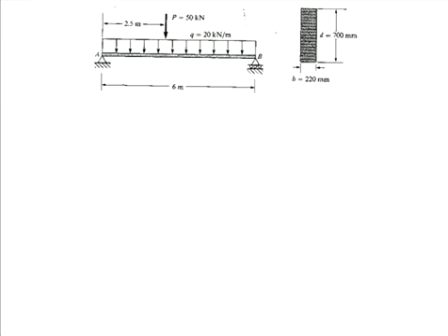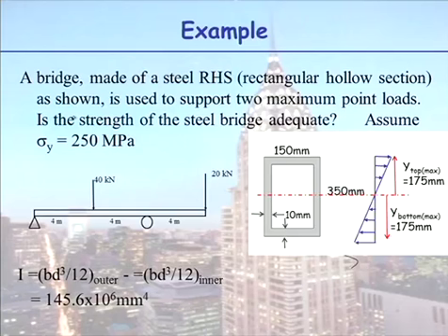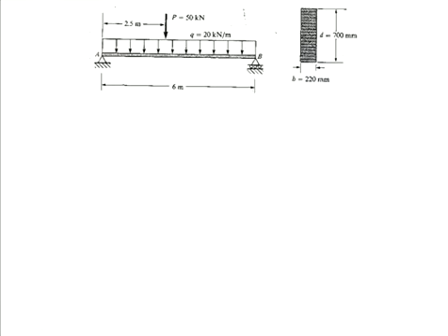Okay, so we just have to use our bending stress formula. So, stress is M on I. M we said was 160. Now, the units of M was kilonewton metres. And I said I want to work in Newton millimetres.